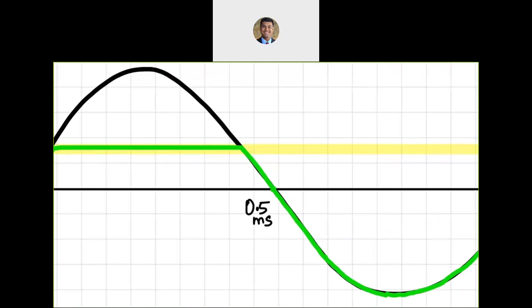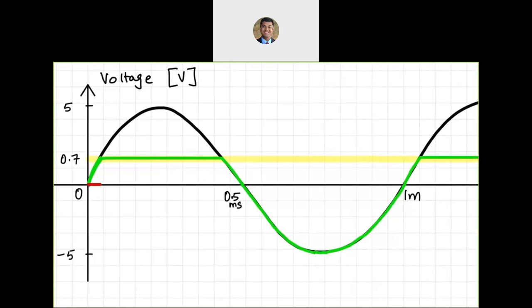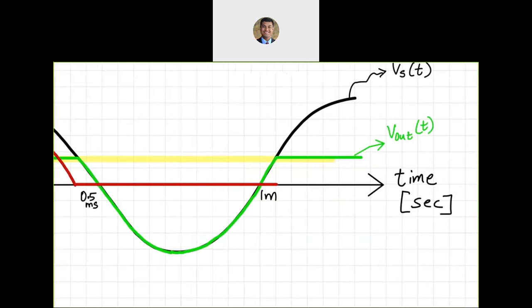And let's do the simple thing first. Whenever it's equal, so from here to about here, again it is 0. In the middle, it'll change. So let me sketch in the middle. When I find the difference between Vs and 0.7 here, it is going to increase sinusoidally and then it is going to decrease over here, and it's going to do the same over in this case over here.